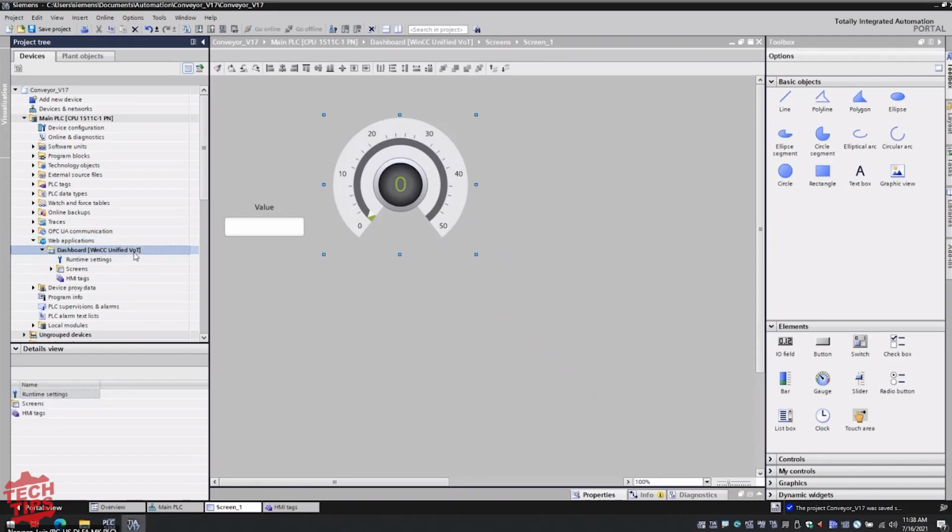Now, let me ask you a question. PLCSIM comes with TIA Portal included. PLCSIM Advanced is an additional charge. Do we need to use Advanced to simulate the VoT screen? Yes, you do. Exactly. The Advanced allows a lot more functionality, like being able to simulate a lot of the communication functions of the PLC, and that also includes the web communications. So the web server and everything is part of that. Okay. Whereas PLCSIM is pretty limited on what it can simulate from a communications standpoint.